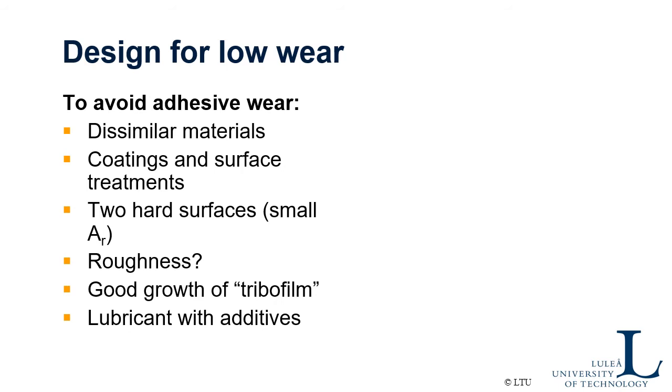You may also have two hard surfaces in this case, also for adhesive wear, because then you keep the real area of contact small. And as I said about roughness, if you make it too smooth, it's a big risk of adhesive wear. On the other hand, if you make it too rough, you may end up in abrasive wear.